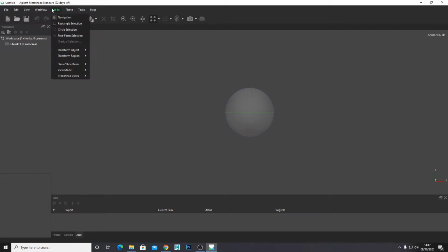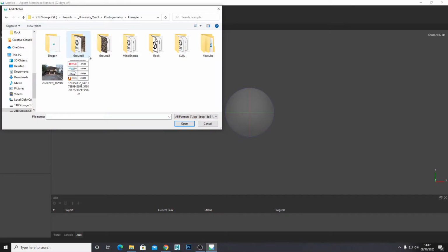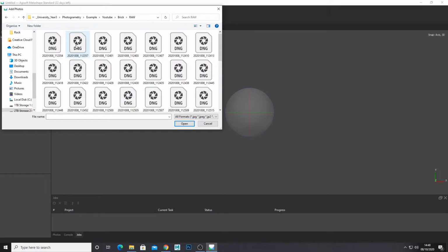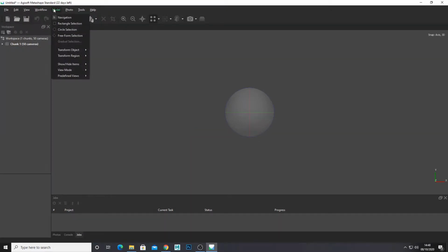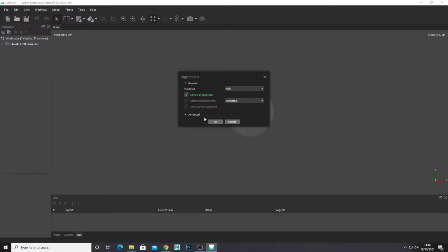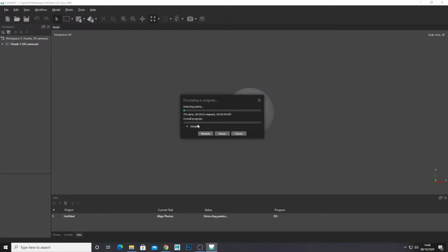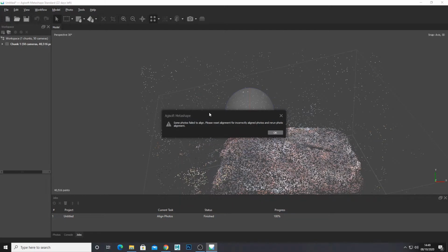For the purpose of this tutorial, I'm just going to slap the images into Agisoft Metashape and see how they turn out. Once you've imported your scan images, you want to go to Workflow and Align Images. This generates tracking points that images have in common, and from there works out the camera position. Okay, it's now generated some tracking points and aligned the cameras.